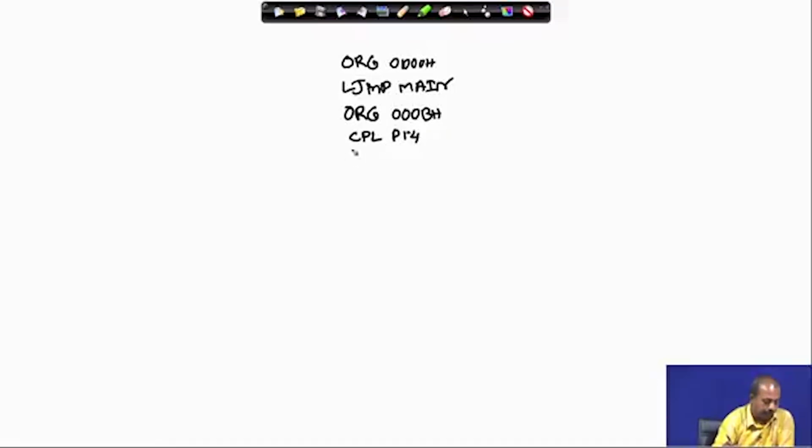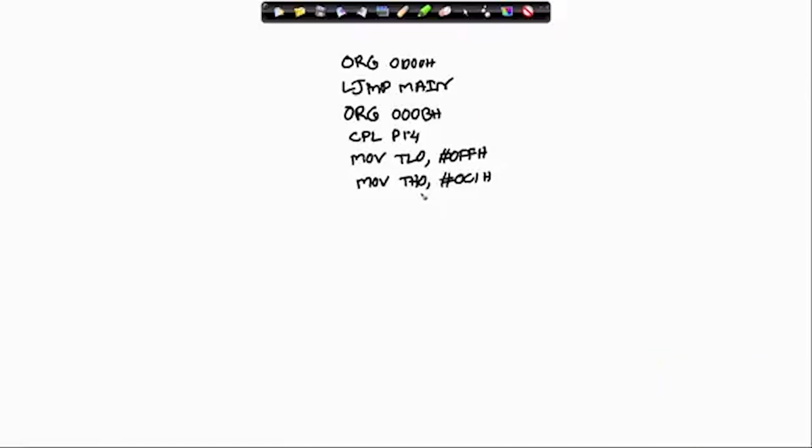For that purpose, I have to move TL0, comma, hash 0FF hex, and I have to move TH0, comma, hash 0C1 hex.